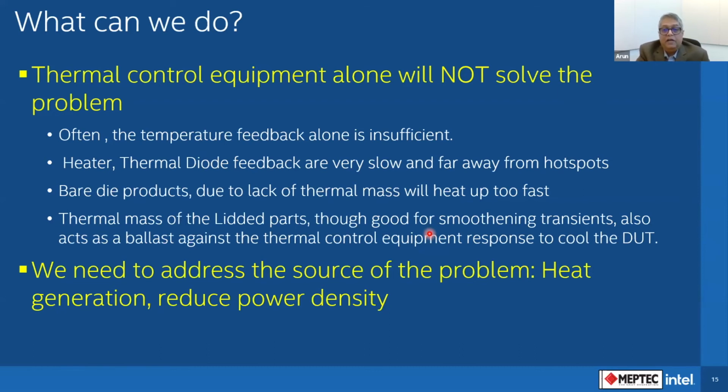It's not usually microseconds. Maybe the damage is being done at microsecond scale, but the tests are long. The test could be anywhere between 2 to 3 seconds because of your cache patterns, especially array patterns. In fact, you can run cache patterns for 5 seconds, 8 seconds non-stop, and during that time it is very difficult to monitor temperature. The only way to find out that something is going wrong is after the damage is done: the thermal runaway happens and the tester says, I'm drawing too much power. So the tester shuts down because too much power is being drawn, by which time the wafer is burnt or the probes are melted. So this is a huge problem on wafer test.